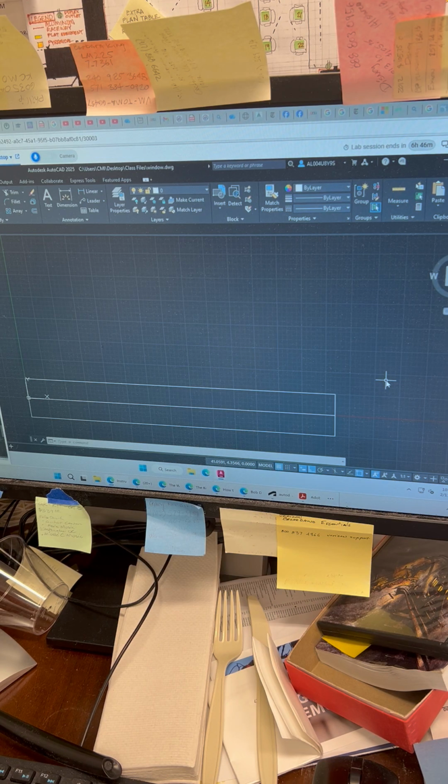Okay. Alan, I've got a question. Yes. This is Matt here. Okay. When I start the line, I put it in at 0, 0, right? Yep. And then 2.5 for the next one, right? Yep. And then it keeps going back to the bottom there. Now, let me put this on the screen so everybody can see this. You're fine, but you are way zoomed out. Now, look at your units there. They're 300. Oh, that's it.